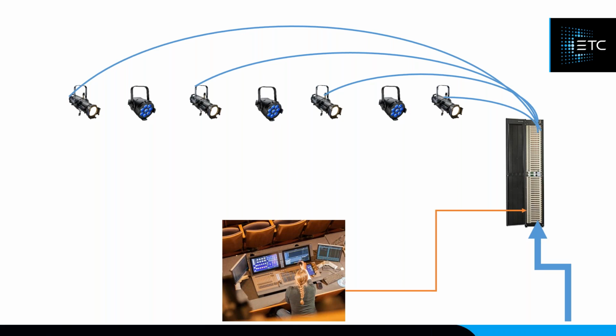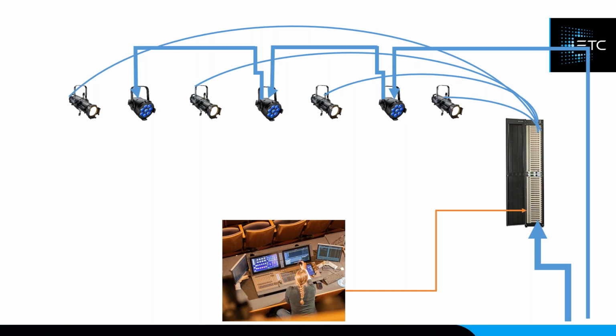So now we're going to hang some LED lighting fixtures up with our standard light bulb fixtures. So we put these 3 lighting fixtures in there, so now we need to get power to them. Well, LED lighting fixtures don't work well with dimmed power. In a lot of cases, you don't want the power run through a dimmer, even if the dimmer's at full. That's not what they need. They need their own separate electrical system. So now I've got to start all over again, and I have to run constant power, power right out of the wall that hasn't gone through a dimmer to each one of these fixtures.